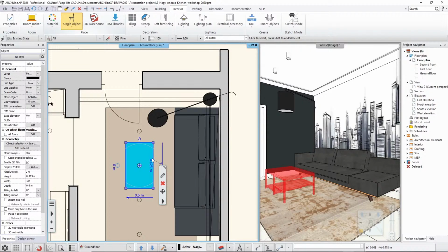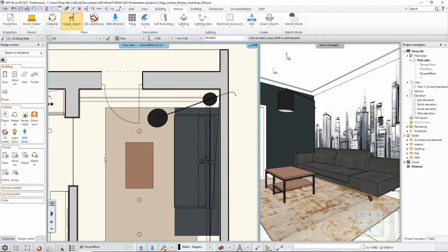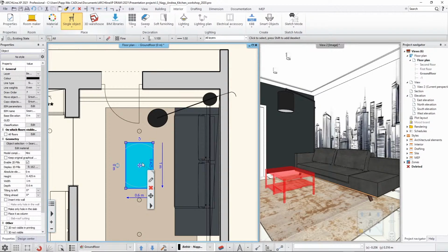And also here, just to make sure that whenever I change this, it won't fall under this other item, I will simply go there and say that the 2D fill is enabled, and then the draw order should be at least number 7, above bottommost. Now, in case I do that, there might be another issue with the other unfilled objects as well, like these here, that they got overlapped, because simply the same thing happens with all the rest of the objects.